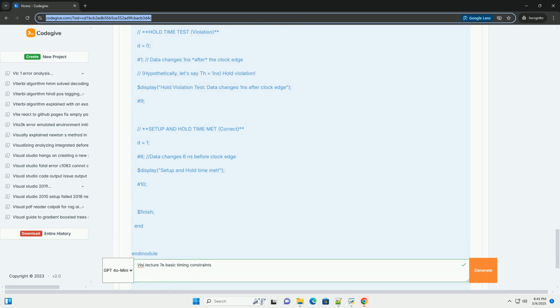Let's illustrate with a simple example of a D flip-flop and how setup and hold times play a role. We'll first create a D flip-flop module, and then we'll demonstrate a hypothetical scenario. Now, let's create a test bench to demonstrate setup and hold time considerations. This example is simulated timing, not actual physical timing, so it's conceptual. We'd use static timing analysis tools in a real design flow.